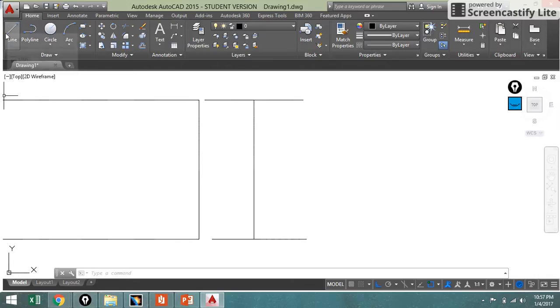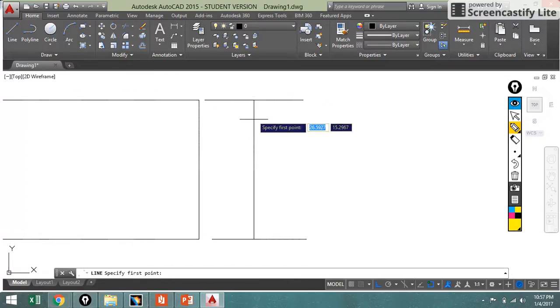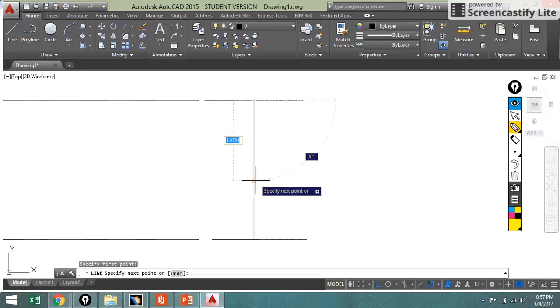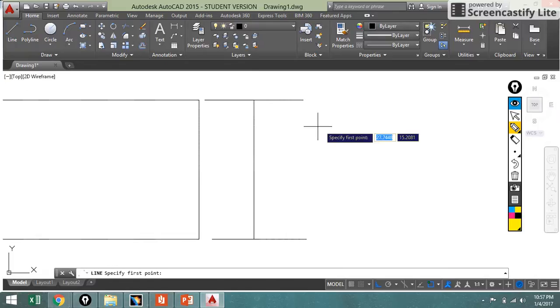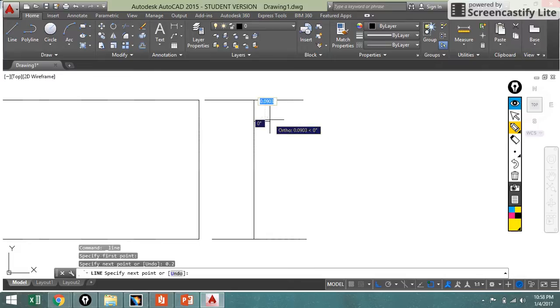Now when you are giving arrows, I said it must be a 1:3 ratio. That is what I said, 1:3 ratio. That means if you take 1 mm length, you need to multiply the distance 3 times. See here, right now I'm taking a line somewhere nearby, and the height of the line is 0.2, and I'm giving enter.